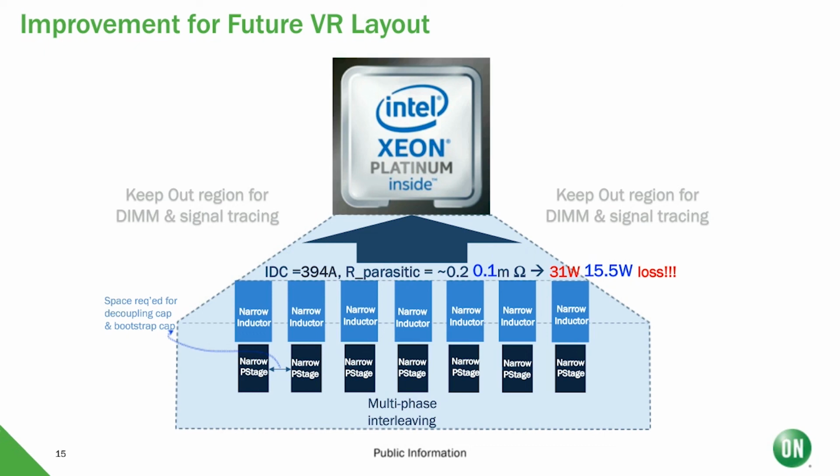So that's why, more than a few years ago, it's probably been a decade, the industry has been exploring the idea of migrating a traditional 12-volt backplane or bus bar to a 48-volt one, so that we can keep the input current low and not have to grow the size of the backplane that much. I hope this answers the question.